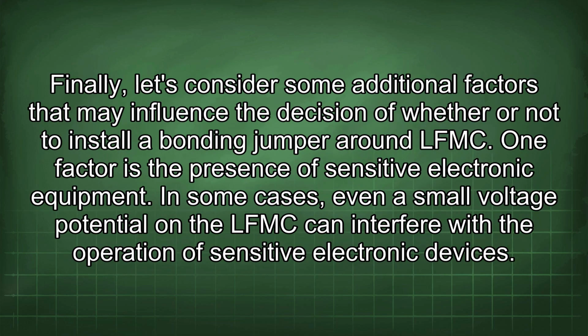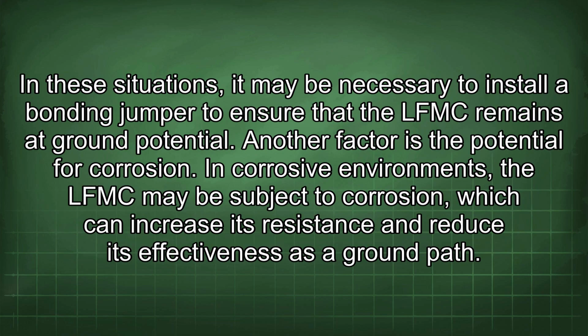Finally, let's consider some additional factors that may influence the decision of whether or not to install a bonding jumper around LFMC. One factor is the presence of sensitive electronic equipment. In some cases, even a small voltage potential on the LFMC can interfere with the operation of sensitive electronic devices. In these situations, it may be necessary to install a bonding jumper to ensure that the LFMC remains at ground potential.